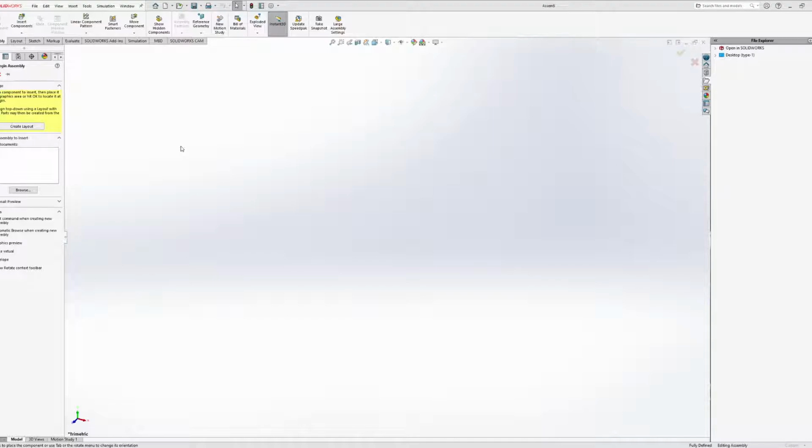The three parts that I just have out here normally are this guide, if you can kind of see it. We have a guide, a plate, and a rod. And now I want all of these things in my assembly. There's several ways that you can do this, but one manner is you can just control left click all of your parts. And what that will do is that the second I hit open, it will populate this open documents drop down. And then it'll just one by one allow me to insert these parts within the graphics menu.